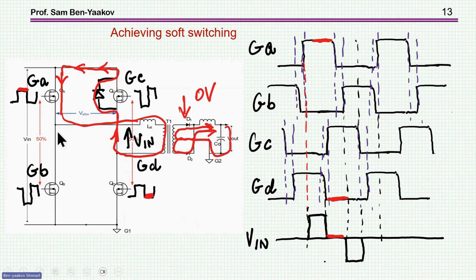So now this thing is locked. While being locked, very important to realize that the voltage at the output is zero, because now the two diodes will be conducting. And since the voltage here and here is the same, then the total voltage is zero. So we have zero voltage across this inner part here. And the inductor, this is the one that I was talking about and doing the whole job of this phase shift, is now actually causing the current to circulate here.